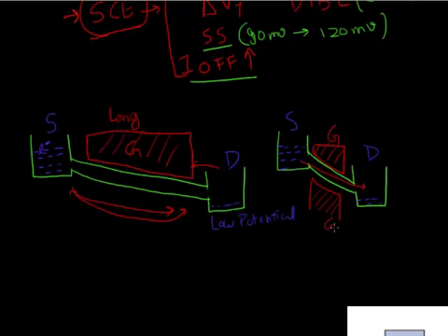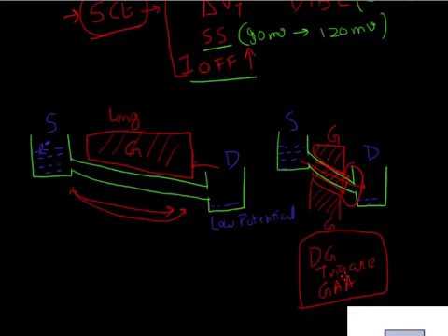So maybe use two nozzles, or use a double gate device, or maybe put another nozzle on the side over here, or use a triple gate or tri-gate device, or maybe put a nozzle all around it, and use a gate all around device. That's a very good analogy to understand why there is a need for these devices with improved electrostatics to improve the short channel effects.